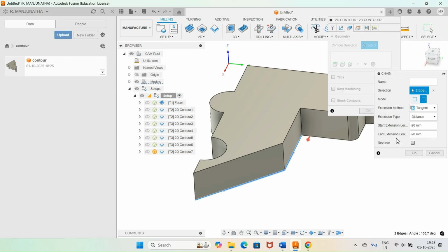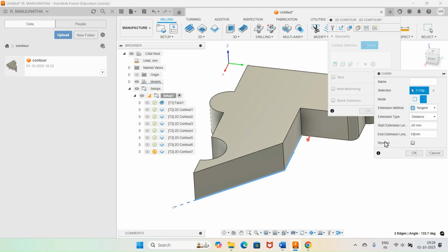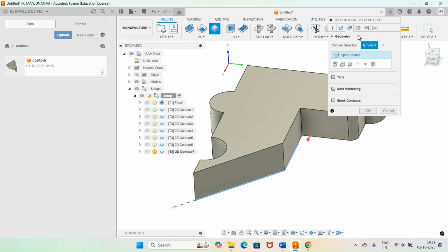Then you just pause it and take around 10 mm on this side, or you take 15, because finally it should pass through it. Okay, so it starts from somewhere around, because already I have removed so much material. So minus 20, no, I will take around 10 only, so that it is safe and you avoid the material there.